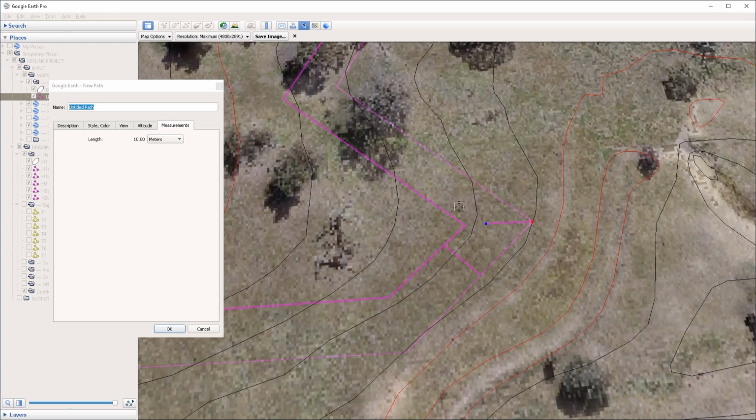So if I try to then connect these angles, I'm inevitably going to get a smaller width than the one that I actually determined. So never make the extensions from the angles, always from the straight segments in between the points where the line breaks. And this is going to be more pronounced on angles that are more acute, whereas on angles that are not so acute, then this is not going to be so visible. But in the end, you're still going to get offset that is not the width that you actually wanted.